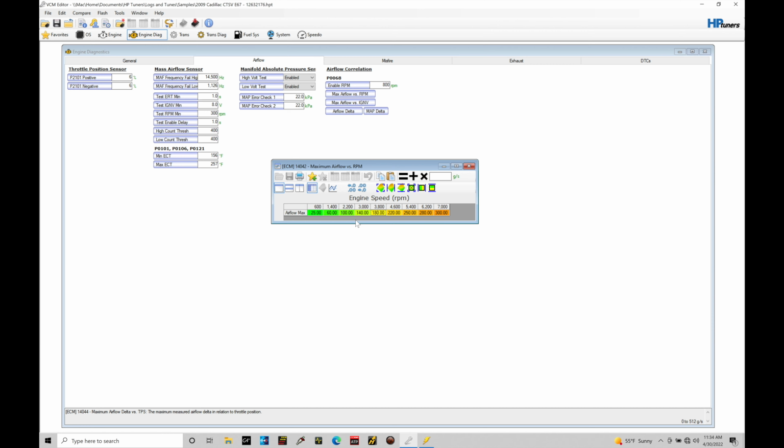So you can imagine at something like 3,000 RPM, if we're at 50% throttle or 80% throttle, for example, we'll have a certain amount of airflow coming into the engine. Whether that's going to be 140 grams per second is to be seen. We need to go and reference what data logs will show us from our VCM scanner. But if we exceed this amount of airflow in grams per second in our dynamic airflow parameter, it will go into the fail-safe shutdown.